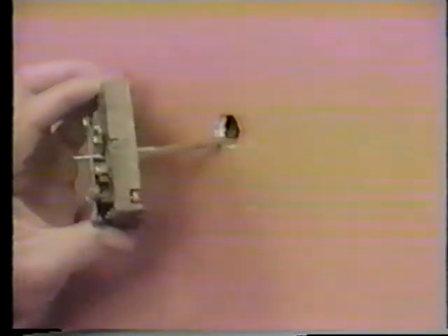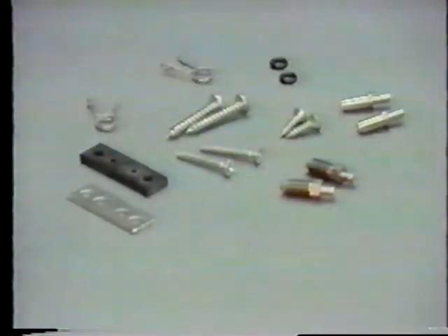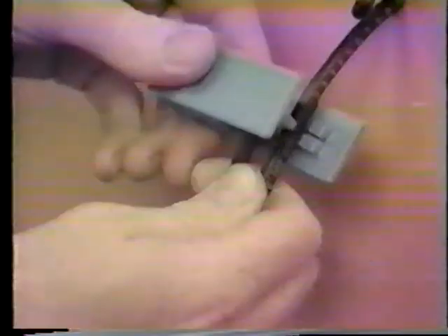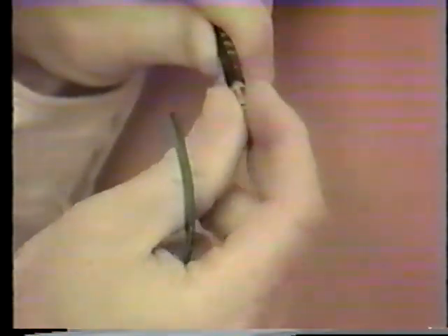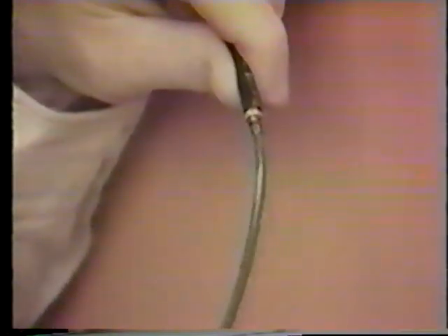Next, remove the old thermostat and any bracket from the wall. Determine the appropriate fittings for connecting to the pipe head. If the fittings in the kit will not directly attach to the pipe head, then it will be necessary to cut off the old pipe head and connect directly to the tubing. Connect the 3/16" OD Tygothane tubing to the pipe head adapters or directly to the tubing.